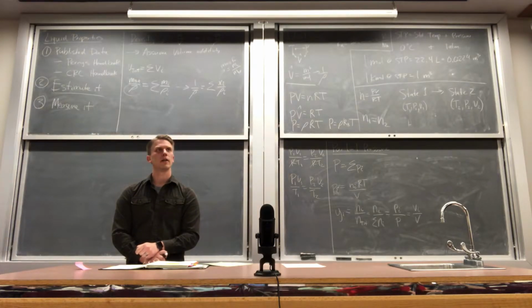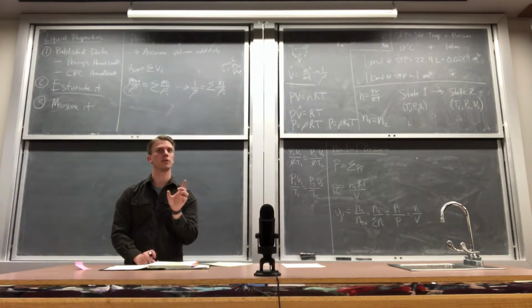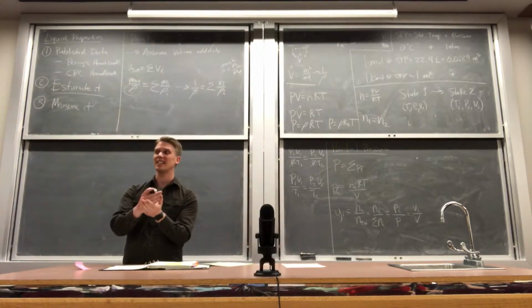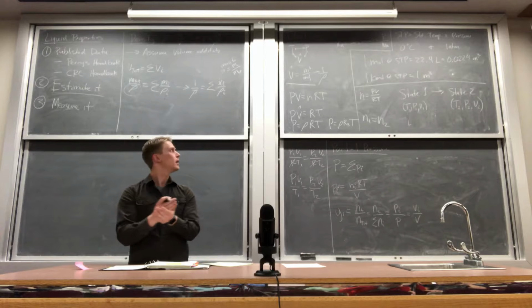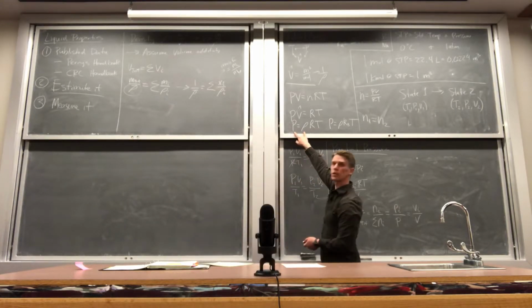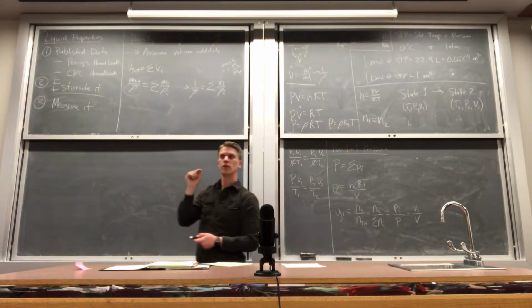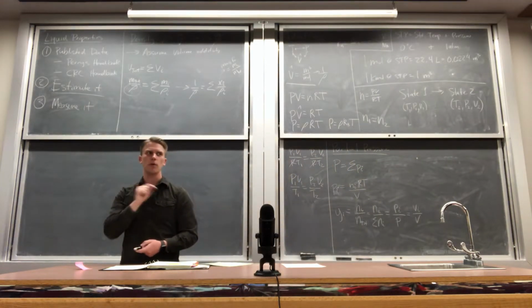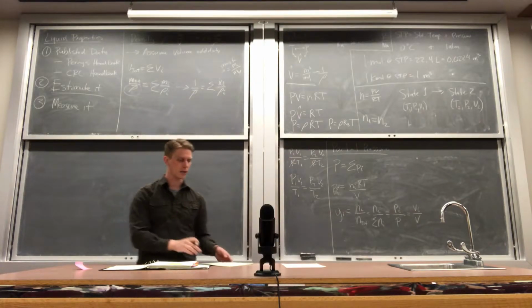Gases are incompressible. No, so almost all gases will be compressible. So fluids, though, in general, we will assume that liquids are incompressible. And what that means is that the density is a very weak function of the pressure. But in the case of an ideal gas, we can see that the density and pressure are directly related. But for a fluid like water, we assume it's incompressible. I think we've hit the most important ones. Now, the most important one that we care about is no interactions.